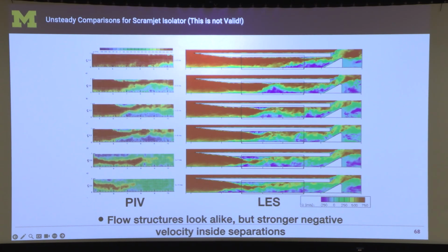So what it reflects is that there are shocks inside the system, and this is the flow that feeds into the scramjet combustor. And those shocks are slowly moving upstream. They're moving towards the inflow. And when they reach the inflow, the scramjet will fail. That's called scramjet inlet unstart. Okay, so this is what will happen.